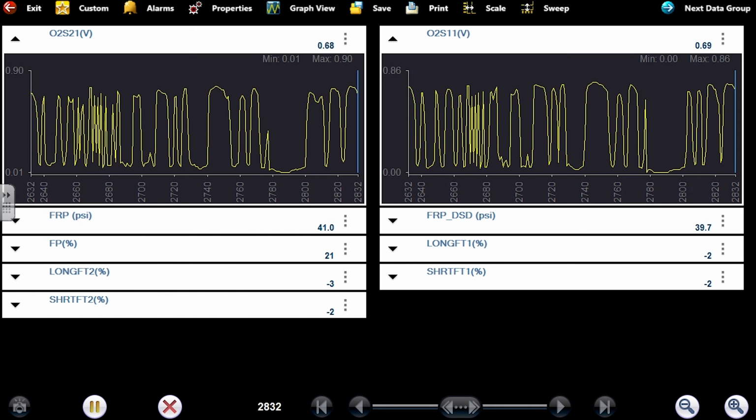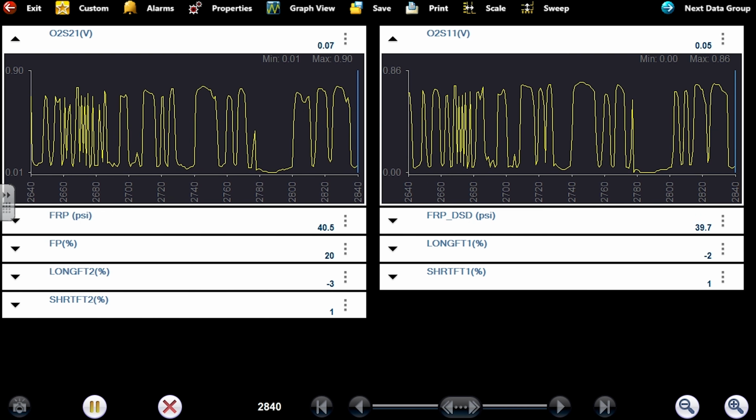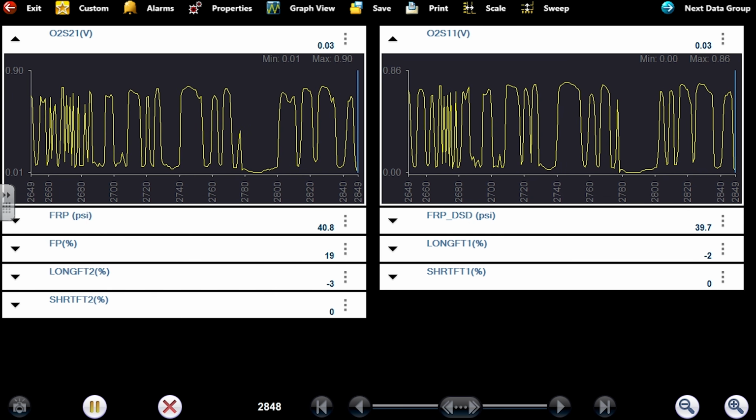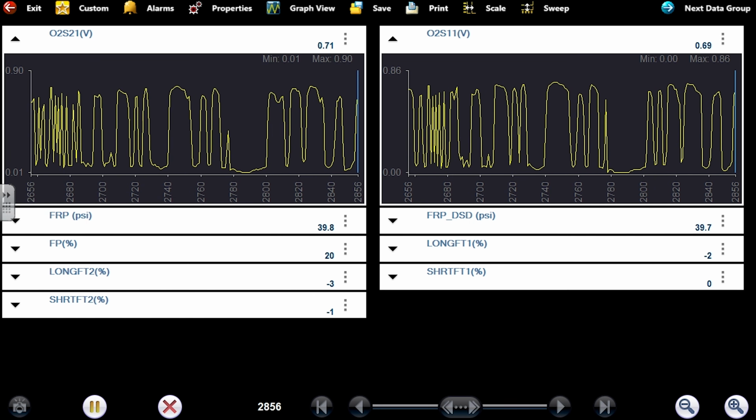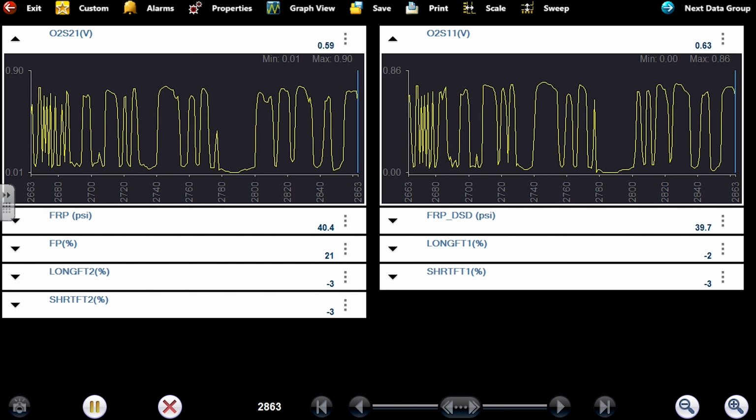In this circumstance, with these other codes, it is the engine running poorly that's setting a MAP code. I'm sure of it. And so I'm not even looking at the MAP sensor right now. That was a long explanation for why I'm not looking at the MAP sensor or worried about that data PID.